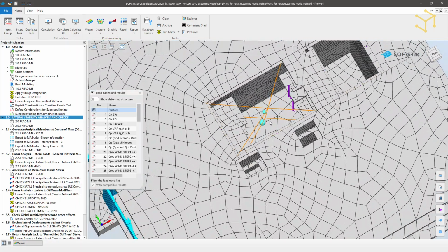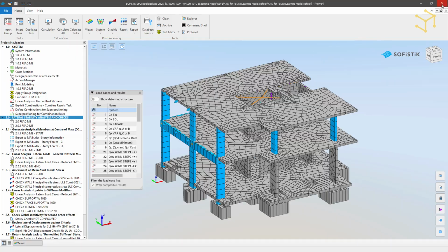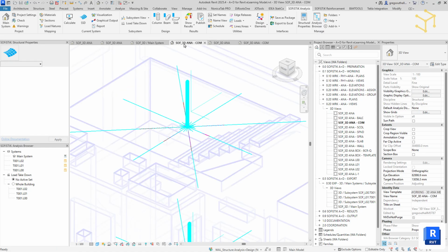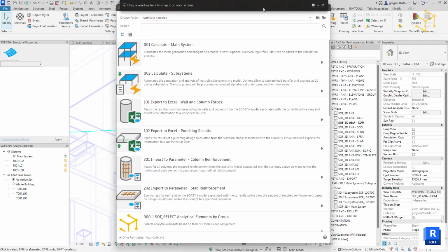1. The center of mass and its location projected to each story level. 2. The story level forces throughout the structure. And 3. The summary of the basic load cases: so the desired percentage of self-weight, dead and variable live loads can be extracted and applied as horizontal components for the notional horizontal loading.